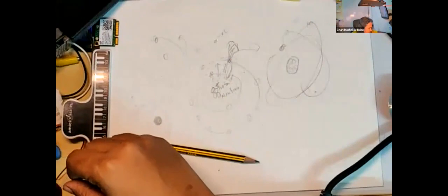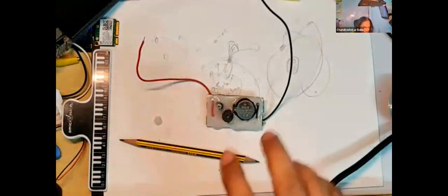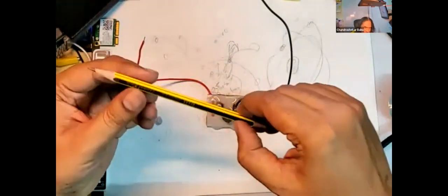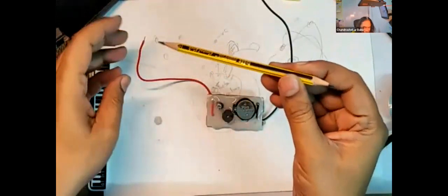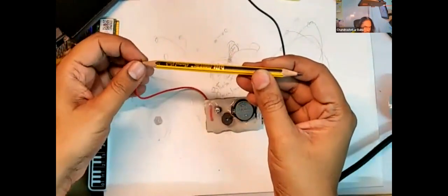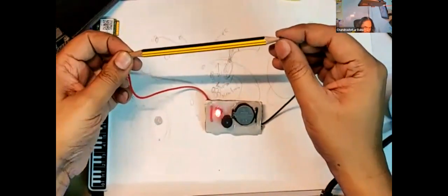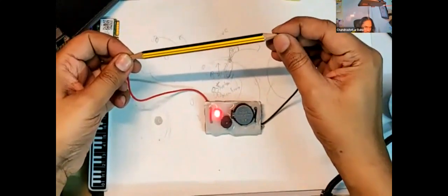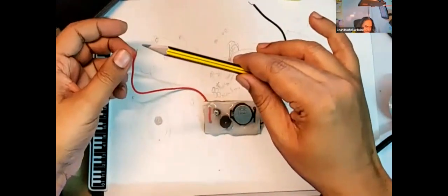I have a small circuitry to show that. I will tell you how to create this. There's a continuity tester. You can use this to find out whether something is a conductor. I have a pencil here. I have sharpened both ends of this pencil. To know whether it's a conductor or not, you can just put one side of this pin here, and the other side, if it's a conductor, you can see it gives a very mild beep sound, and you can see the LED glowing, right? The light glowing there. So this is a conductor.